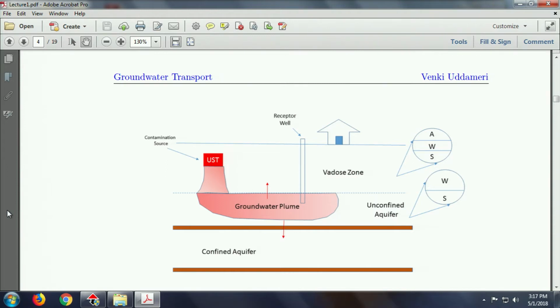Both of them are problematic. The trench is expensive, and sometimes it's not possible. If I want to put it right underneath this house, chances are that property owner will never let me destroy that house and put a trench. They'd say, let me find a new engineer to work on this project, you're out. So sometimes we can't do that. But if we don't place the well correctly, we are putting chemicals in the wrong place. So that doesn't help either.